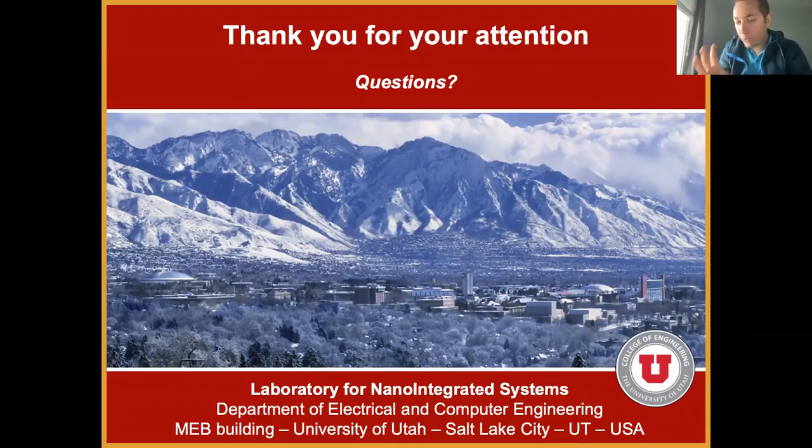So MIGs demonstrate benefits, but we're not at a point yet where we are doing exactly what commercial tooling would do in terms of behavioral synthesis, where you would look for your adders, transform them into a Boolean network, remassage them with mockturtle or whatever, and then bring things back through Boolean matching into the specialized resources.